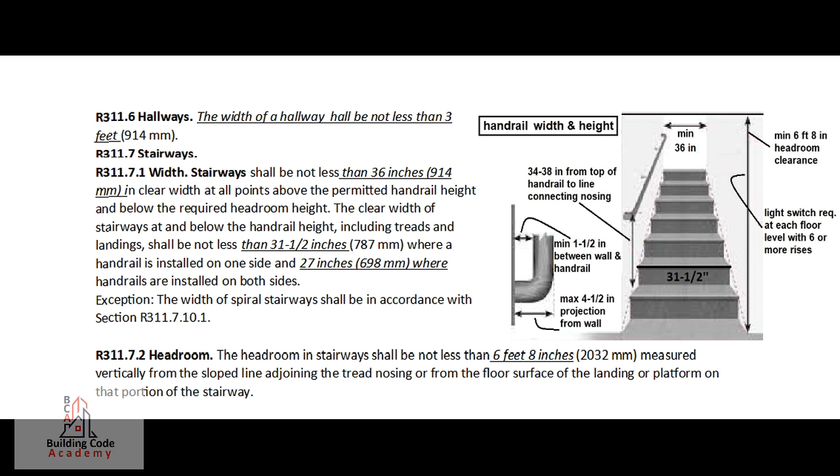R311.7.2 Headroom. The headroom in stairways shall not be less than 6 feet 8 inches, 2,032 millimeters, measured vertically from the sloped line adjoining the tread nosing or from the floor surface of the landing or platform on that portion of the stairway.